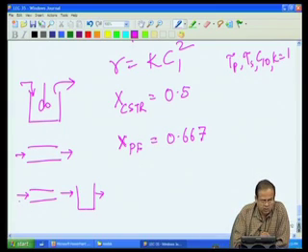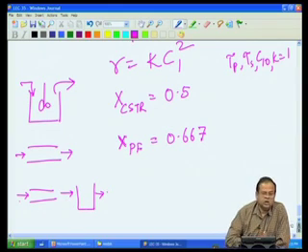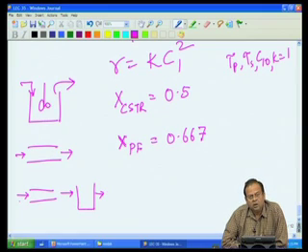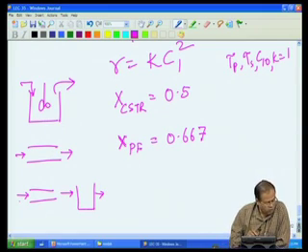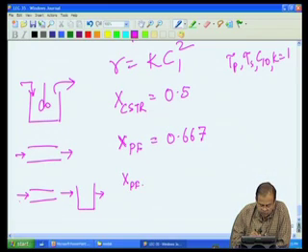Calculate the concentration at the exit of the plug flow reactor, take that as the inlet concentration for the CSTR, and using the CSTR mass balance calculate the exit concentration from the CSTR. We will get X. So, I will now call it PF followed by stirred tank reactor, we get 0.634.